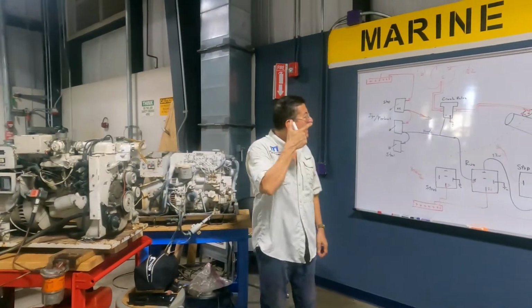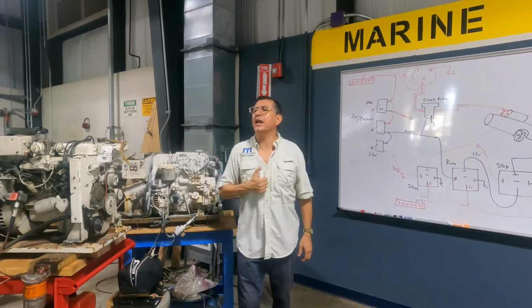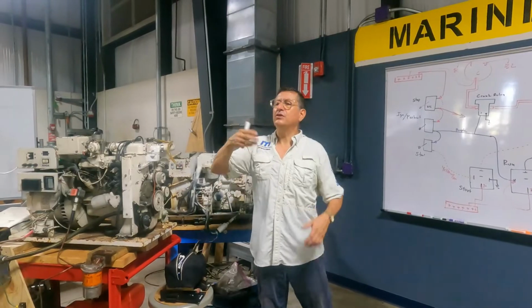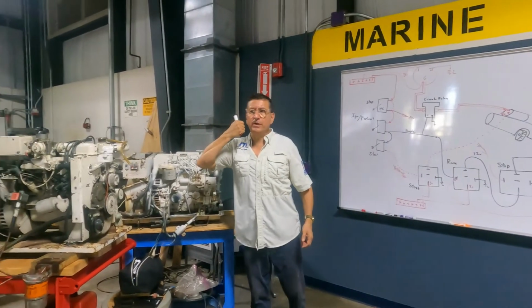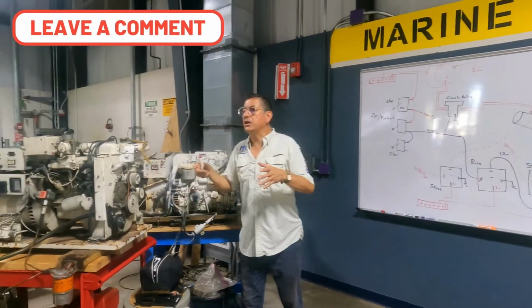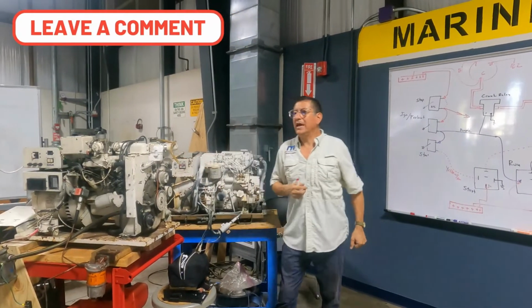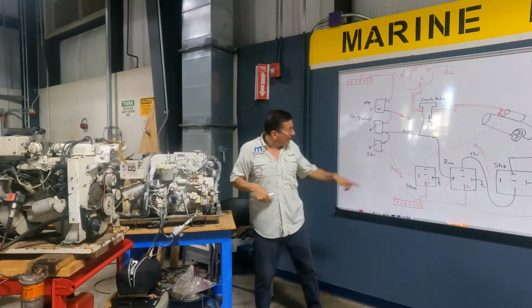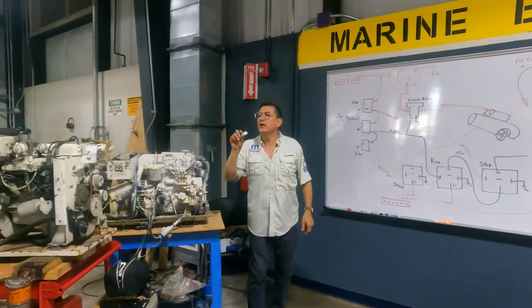Pay attention. My engine only cranks and doesn't start. How can you help? What is your recommendation for the customer on the phone? Hey, my friend, can you go into the control box of your engine? Open the control box. You see three relays? Yes, I see the relays. Do you see the switches?